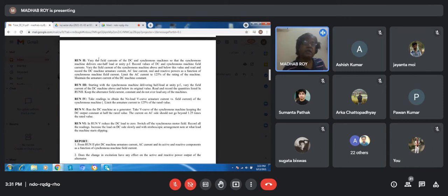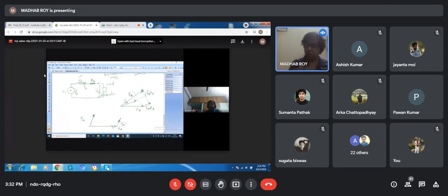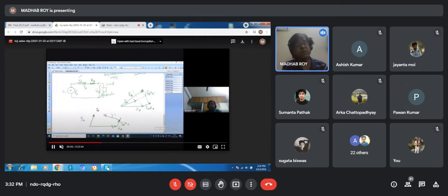In load condition also we can get it, because of the power factor. Suppose the load is very reactive. In the case of a reactive load, one wattmeter can get a positive reading. Reactive load means low power factor. Remember the two wattmeter method: if the angle between the voltage and current goes beyond 30°, what will be the condition of the wattmeter?